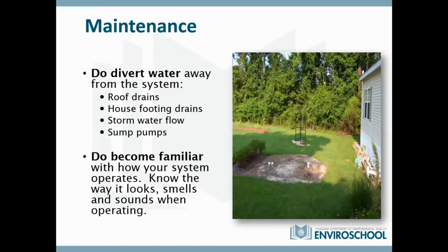Now this one is not talking about hydraulically overloading the interior of the system, but now we're talking about the outside of it. You want to keep water away from the system itself, the tanks and the chambers, and the drain field, and the effluent pipe going into whatever ditch.